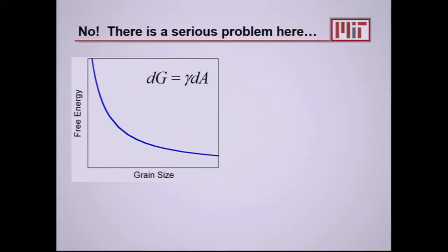And so as we push the grain size down, it turns out to be a parabolic walk up an energy hill in terms of having more internal energy in the material. So although we may diddle with our electroplating bath and figure out a way to sort of trick nature and put a boulder on the side of this hill, all we have done is put a boulder on the side of this hill. And it is not in a stable configuration, and so we should expect that it's going to slide down to the right.